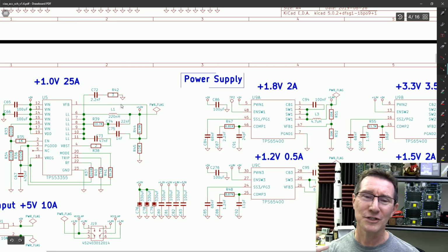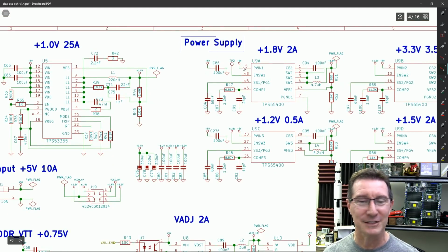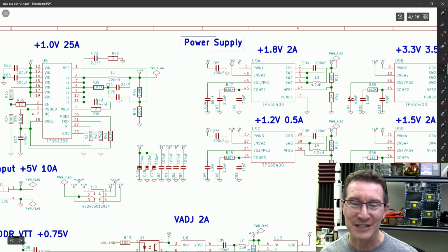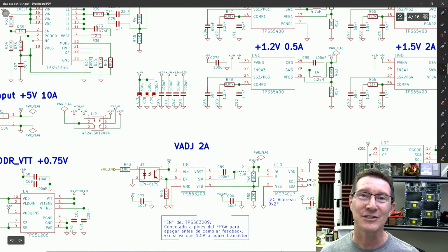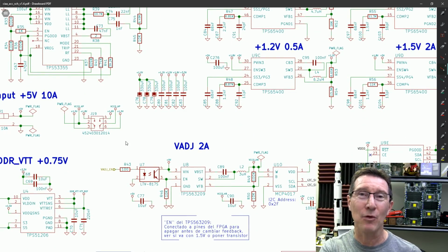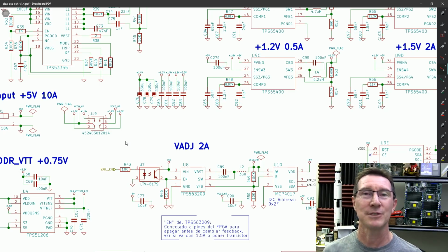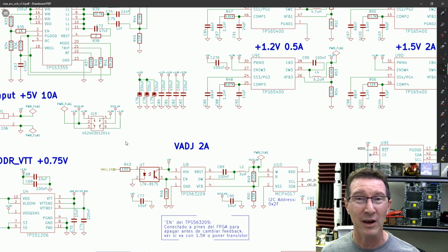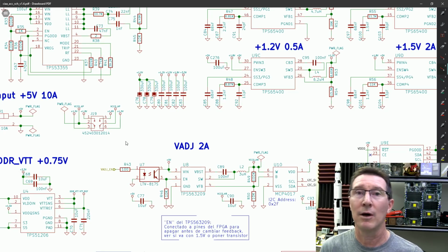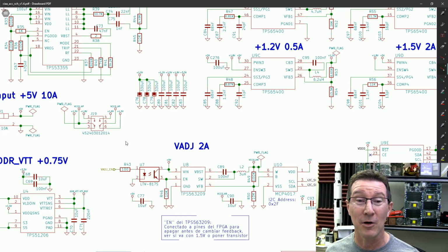And this video was originally going to be me just going through a dozen different open source designs on the market, looking at all the values, going into the data sheets and trying to calculate, can we get away with certain values? LEDs are another classic example. You might calculate, okay, I want 10 milliamps to go through my LED, it's going to be a pretty bright one. And your calculator pops out the value, I need a 680 ohm resistor. Well, I don't know. Does it have to be that exact brightness? Can you get away with a little bit more, a little bit less, to consolidate your BOM items?